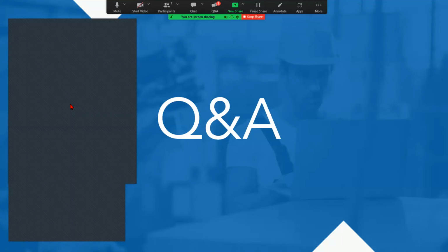So the question here is, does the Sheet Assistant organize based on the order that the views were placed on the sheet? So it will notice the type of view that it is. Say on my first sheet, I placed the floor plan, and then the legend second, so it went 1 and 2. But for the next sheet, if you had it the opposite way, it will identify which is the plan view. So it'll keep that consistency originally from the first format that you had, then the second one. So it will know a floor plan to a floor plan, a legend to a legend. That's how it will know which views to keep aligned with each other.